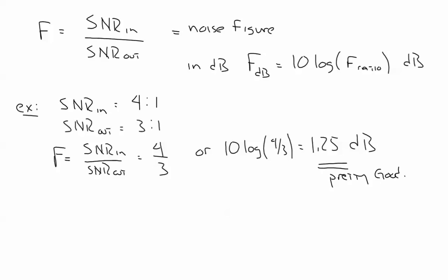All right, remember, a noise figure of 3 dB would mean that I would reduce the signal power by half compared to the noise at the output of my amplifier. In my experience, noise figures on the order of 2 to 10 dB are things I've encountered.